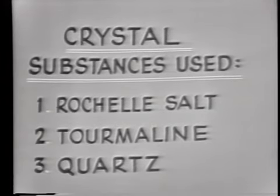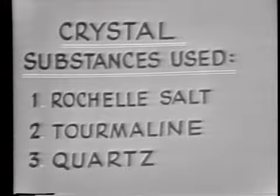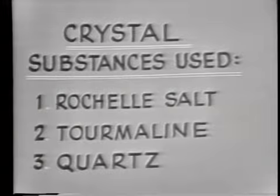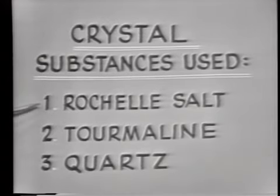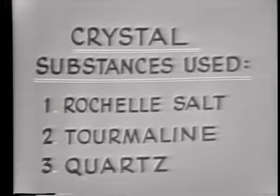Now, let's look at some of the crystal substances that possess the piezoelectric characteristics. They are Rochelle salt, tourmaline, and quartz. We should include these substances in item 2 of the TVI guide, the A part of item 2. Of these three, Rochelle salt exhibits the piezoelectric effect to the greatest degree. However, quartz crystal is most generally used because it has a greater mechanical strength.